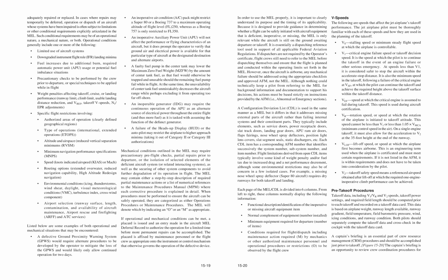If it is not listed in the AFM, it is within requirements and does not have to be taken into consideration by the pilot. V2, takeoff safety speed, means a referenced airspeed obtained after liftoff at which the required one-engine inoperative climb performance can be achieved.